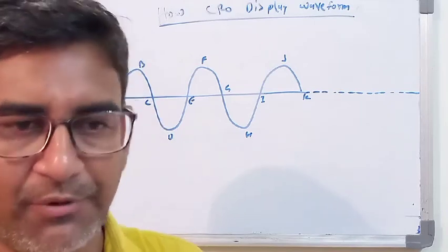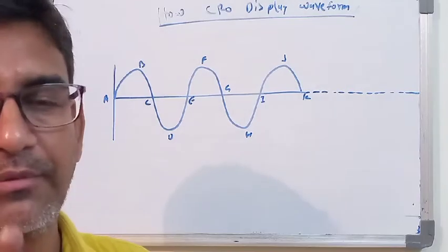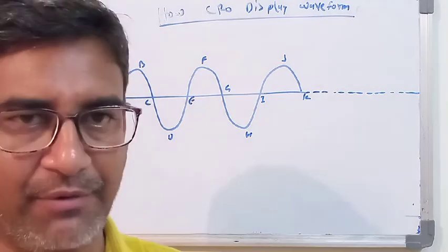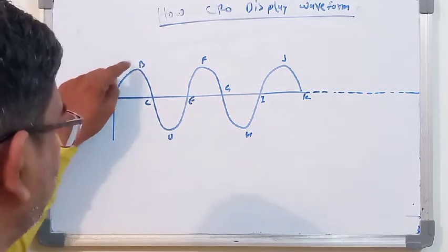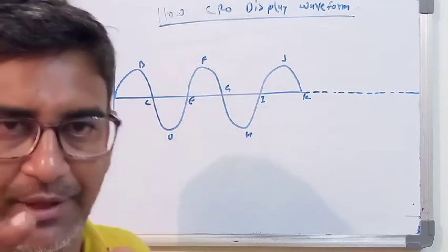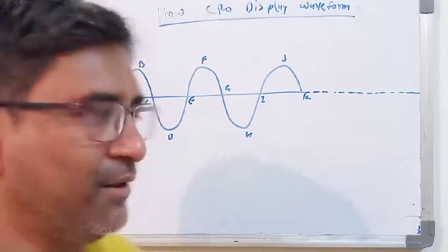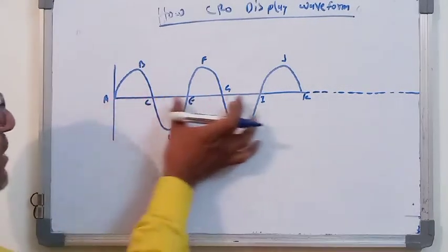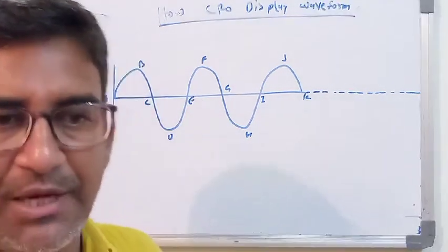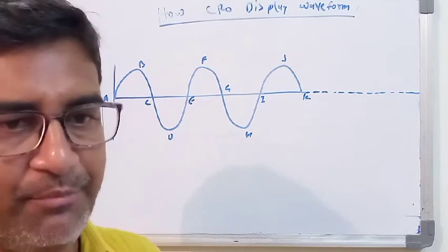With that AC voltage applied to the horizontal deflection plate, the spot moves from the left side to the right side at one particular frequency. The frequency is equal for each and every cycle. Okay, the sinusoidal signal produces a line.